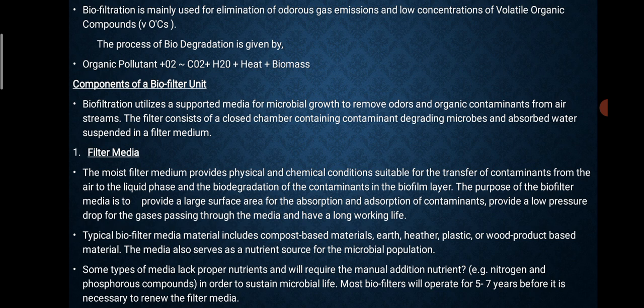Sometimes the media lack proper nutrients and will require the manual addition of nutrients, for example, nitrogen and phosphorus components. In order to sustain microbial life, most biofilters will operate for 5 to 7 years before it is necessary to renew the filter media.